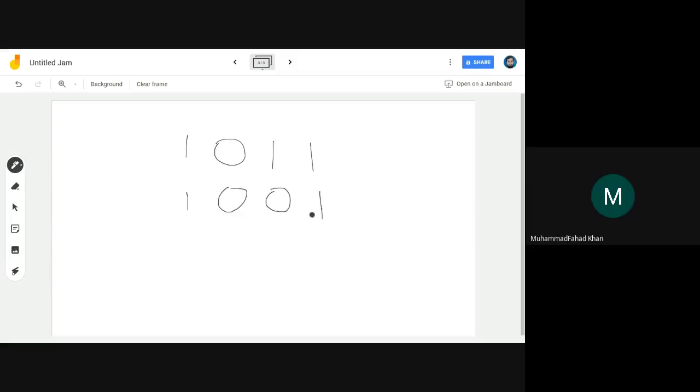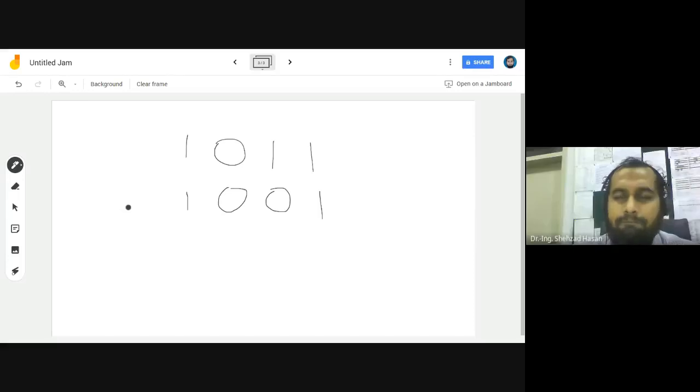Sir, if we take this one as an example, then k by 4 would be a one block adder. Uh, k by 4, no, okay, k by 4 in that case, yeah, that would be the 1 bit adder, right? But conditional sum adder is a little different than that, because in conditional sum adder, what you do is you don't really design it as a ripple carry adder.